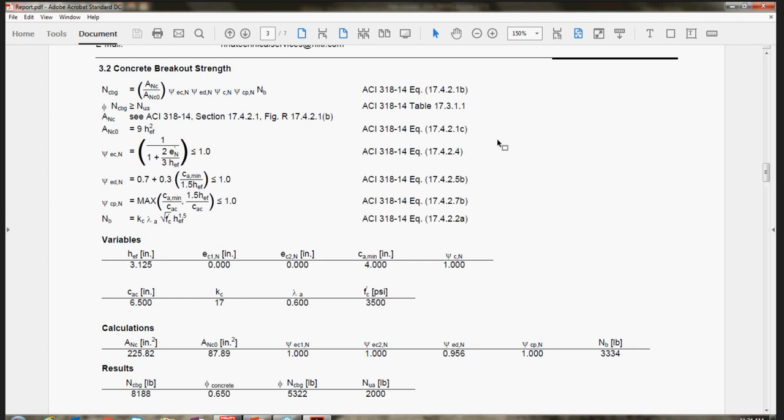Or we could input it down here at this table. It does not matter where we input it. We're going to input our shear load in the negative Y direction and kind of zoom out, double check our geometries. Everything looks good. This is what we wanted to use.